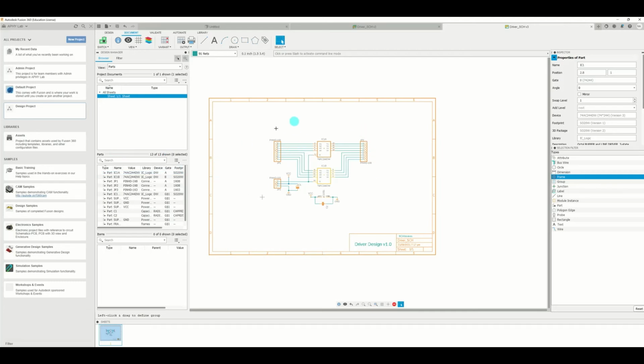The next thing to do, which would be the topic for the next session, is to create our PCB from this by creating a new one and switching to a PCB layout. But you have to link the PCB to the schematic. It's better that you do that in the project itself. When you create a new design, and from the new design you create a new electronic design, they will of course be linked together. That's it. It's actually saved in our Fusion Live folder or team, and anybody who is a member of the team should be able to see this design.